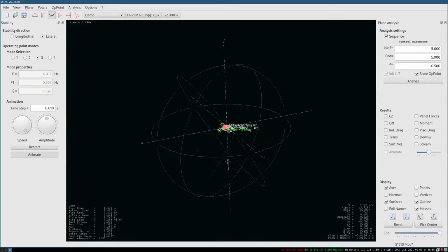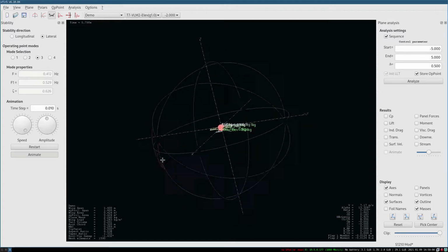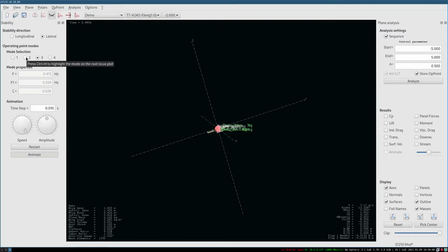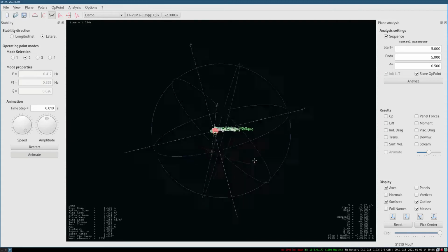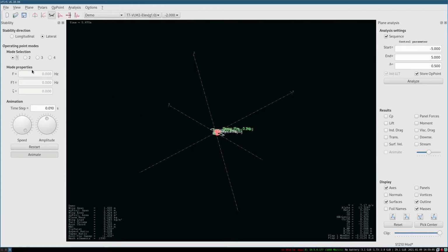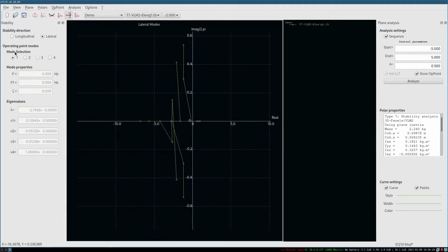Okay, so what we've got here, we've got roll damping. No, that's Dutch roll, isn't it? Yeah, that's definitely Dutch roll, that walking around, and that's probably going to be a roll damping. Okay, so what are the criteria, and what do you really need to look for?